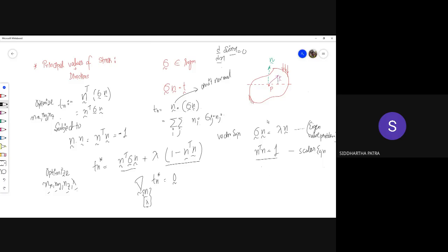So it's a legitimate way of getting the solution. By bringing in the Lagrange multiplier, you're essentially making the constraint equation one of the equations that needs to be satisfied simultaneously with every other equation. Otherwise, nx, ny, nz could be infinitely large, positive or negative, to give you an optimum value for Tn, and there was no solution. By incorporating this constraint equation, you will be able to solve the system. Both sets of equations should be satisfied simultaneously to give you the principal values.